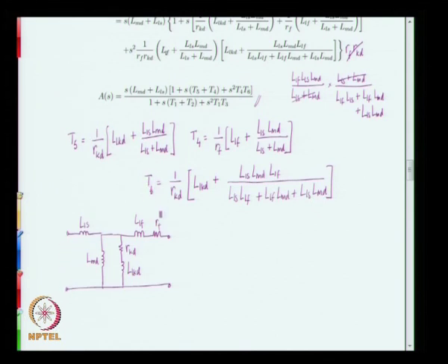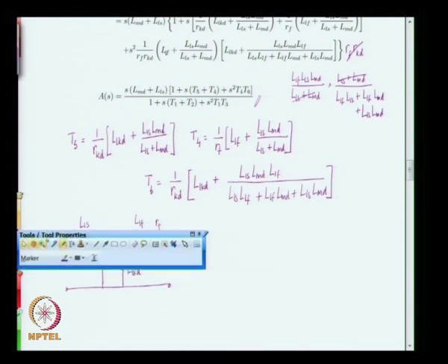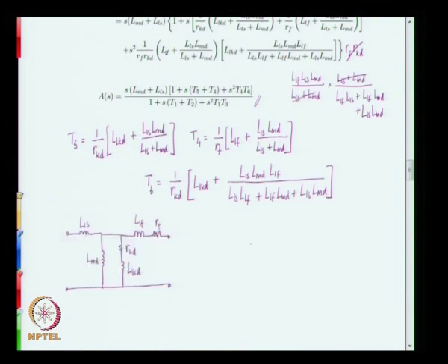And then if you look at T6, what you have is LLKD, then LLS, LMD, LLF. Now if you assume that this is shorted and this is also shorted, and you neglect RF and look at the resistance RKD and see the inductance that is seen by it, then that will consist of this LLKD coming in series with a combination of three inductances coming across each other.